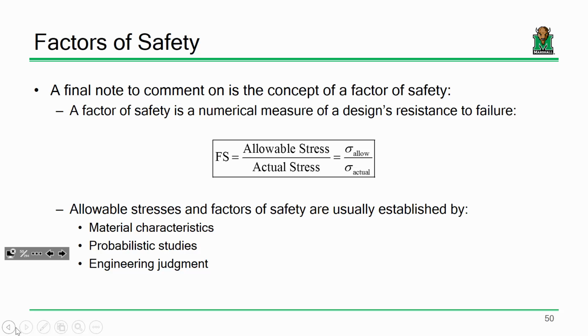The only other thing I wanted to mention is the idea of a factor of safety, okay? Now, in my world, in structural engineering, we really don't use factors of safety the way that you think we would. Now, what do I mean by a factor of safety? I like breaking things. My general philosophy is any day with controlled demolition is a good day. So let's say I took this table down to the lab, okay? I put it under a large capacity actuator, and I started applying force until this sucker wanted to snap in half, okay? Now, let's say it snaps in half at 800 pounds. What I might then do is say, you can only put 400 pounds on it, okay?